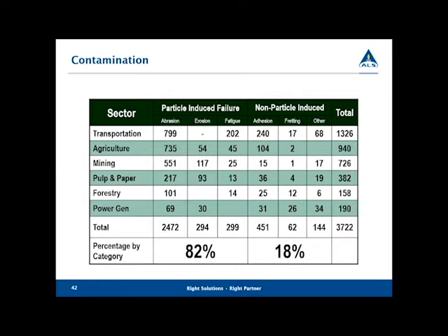So that just begs the question: if this is the case, why don't we spend more time thinking about how we can filter out these problems before they even occur? Dealing with breathers, dealing with filters, and so forth. Spending a little bit extra money on filtration, a little bit extra time on methods that don't introduce particles, can have a huge effect on overall reliability.